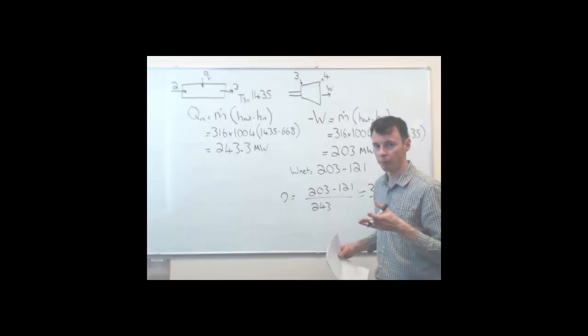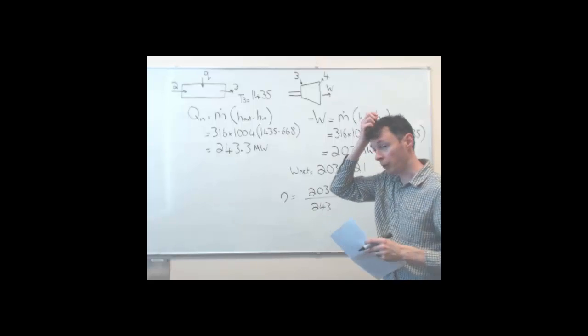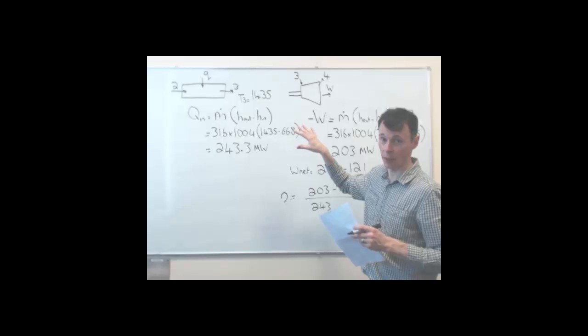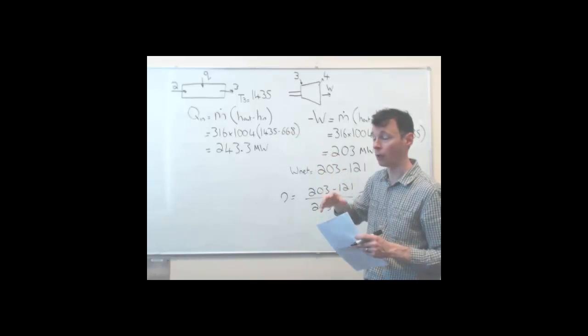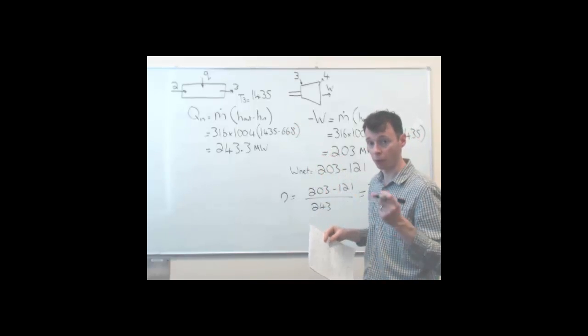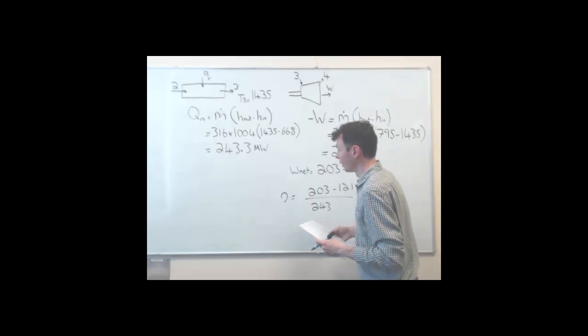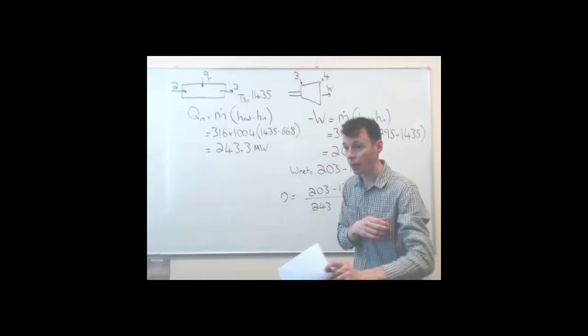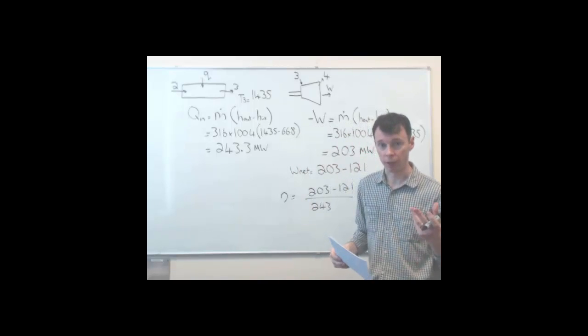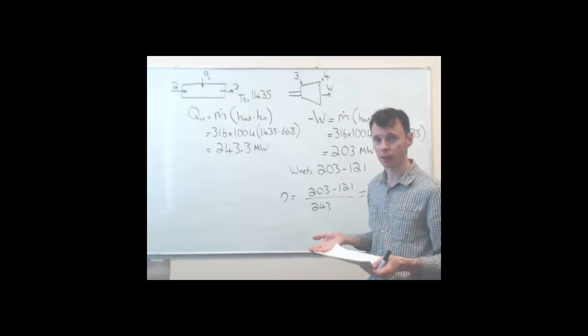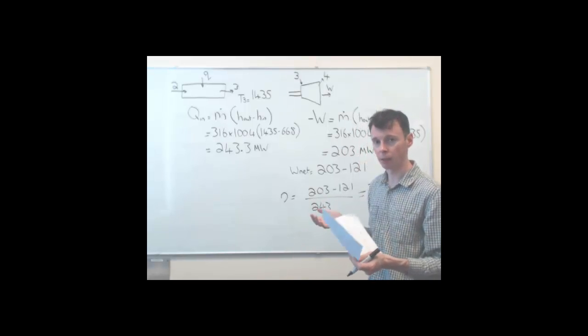Now in the UK, to give you a bit of background, in a lot of places, we used to have power stations that were exactly this, an open cycle gas turbine. So we draw in atmospheric air, compress it down, mix it with the fuel, spark ignition, it went bang, expand out, and then we realised some work from that. The efficiency, 34%, you think, well, gas is nice and hot, surely we get a better efficiency.